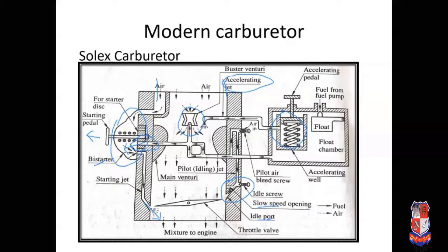When the engine warms up, the starting pedal is again released. So the smaller hole is set to this line. Less fuel enters, right? So the rich mixture is not supplied.